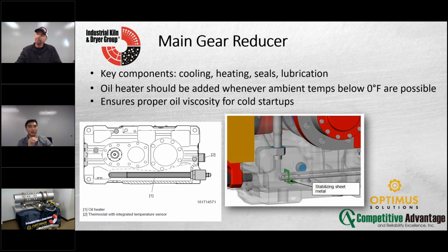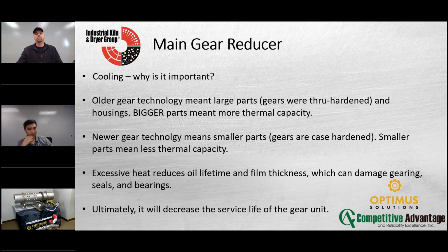The thinner the film, the less protection it has. So that's where controlling the temperature is important, because it'll A, help on the viscosity of the oil, and B, also any odd thermal expansions in the unit. So these are some of the hot stuff.